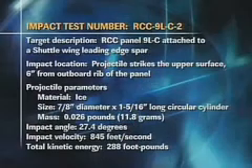The next set of videos I want to show you are ice impacts on RCC, and ice is a little different animal than foam. There's the potential that ice can form on the external tank and be released, and if it's released early enough in our trajectory, it has the potential to cause damage to the leading edge. Again, we perform these tests to try to establish the thresholds. They don't necessarily indicate a likelihood of occurrence.